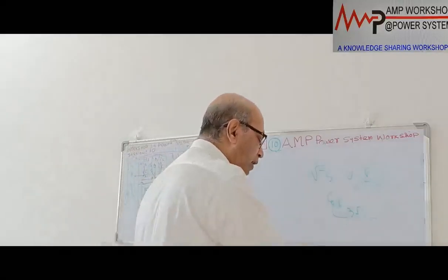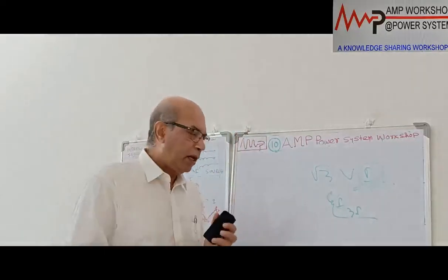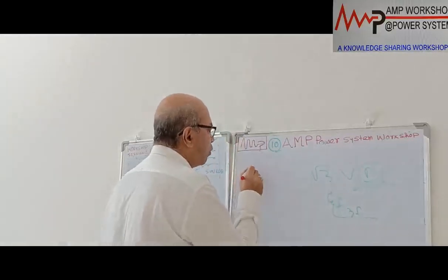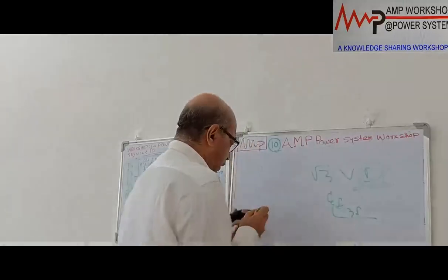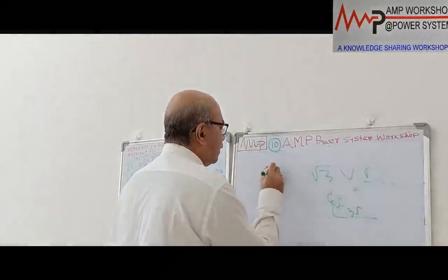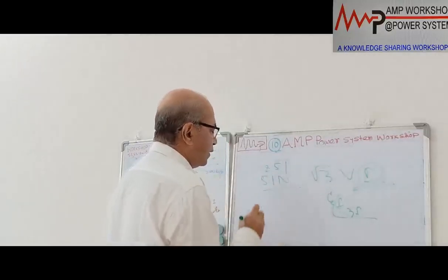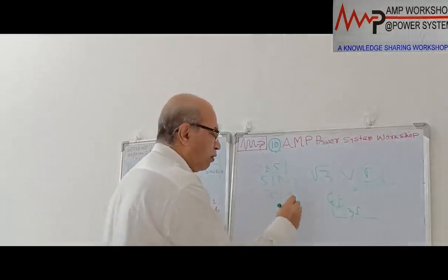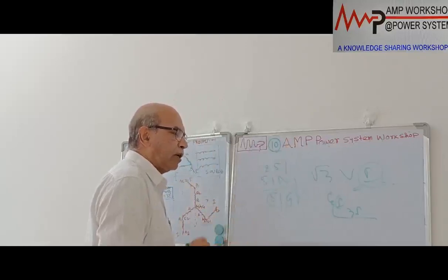This is about the earthing transformer. So we are now summarizing the total things. For the internal earth fault of the grounding transformer winding, for the phase fault we provide 50 and 51 protection, and for the earth fault protection we provide 51 on the residual connection on the phase side and 51G for the neutral side, and these two are coordinated, and these also coordinate with the external earth fault condition on the feeder.